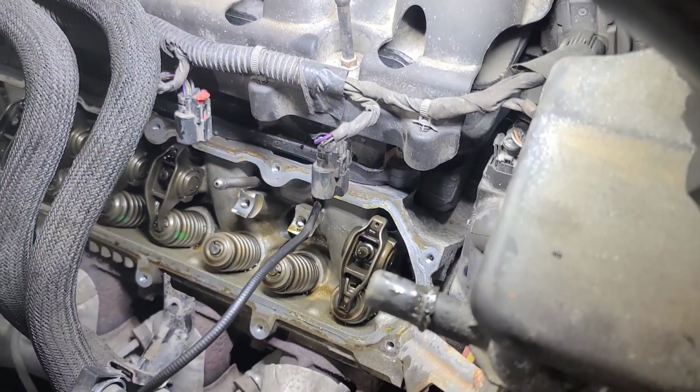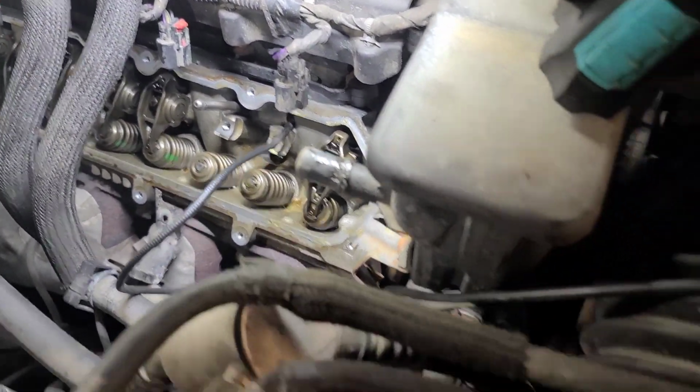So I found an older push rod, a longer one from a different engine, and I inserted it, and I'm looking from the intake side to the exhaust side, and watch when I move this lifter. You can see the lifter is definitely collapsed. The spring is loose. Oh well.